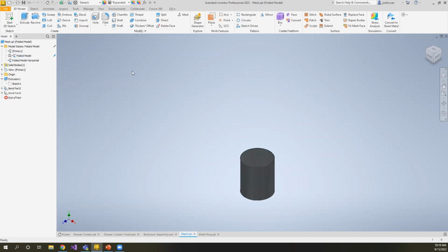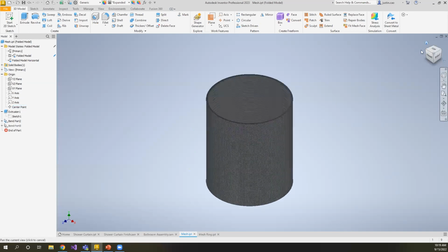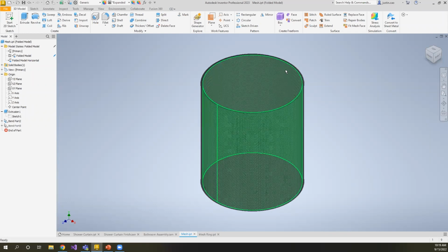So just know also, when you're going into different model states, if you're changing the geometry drastically and you're projecting a lot of geometry on your sketches, if you switch back and forth, you might get some health doctor stuff pop up saying that it doesn't recognize some geometry, because it might no longer be there, or you're referencing something that you might have cut out before or added. Then you might have to work around constraining things to the origin to get things to line up and make sure you don't have anything that's broken within your part.